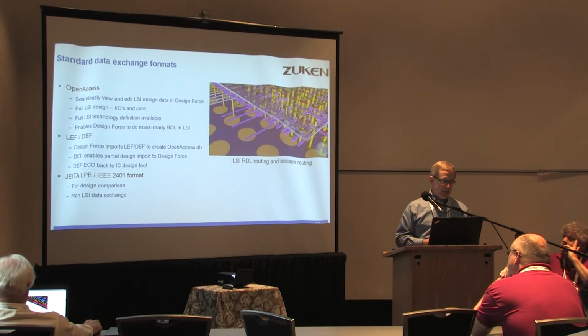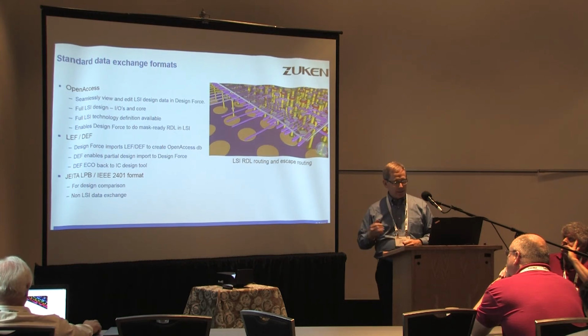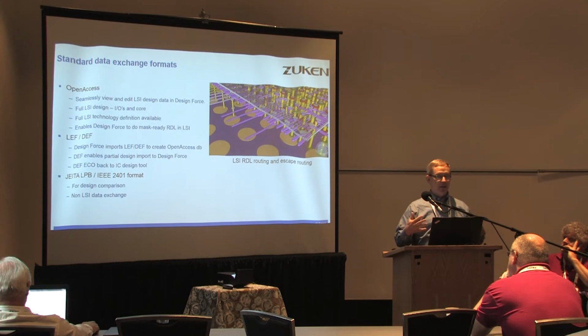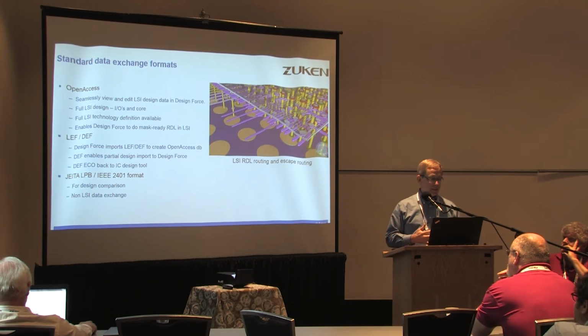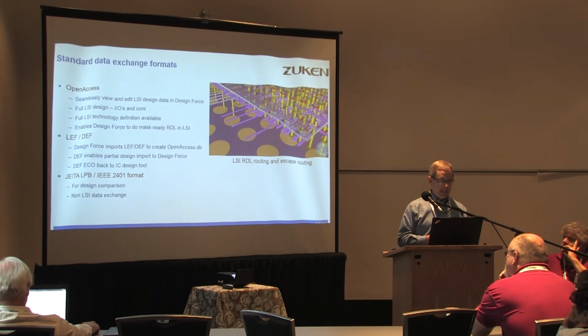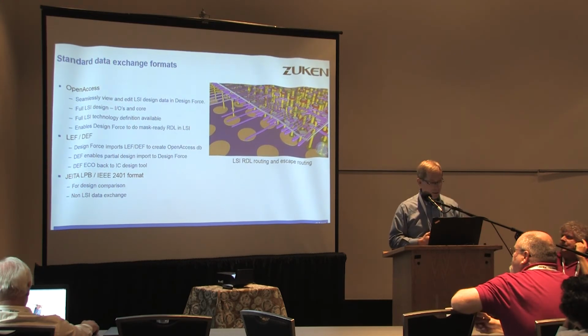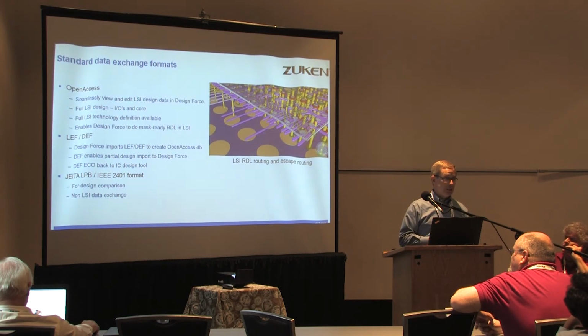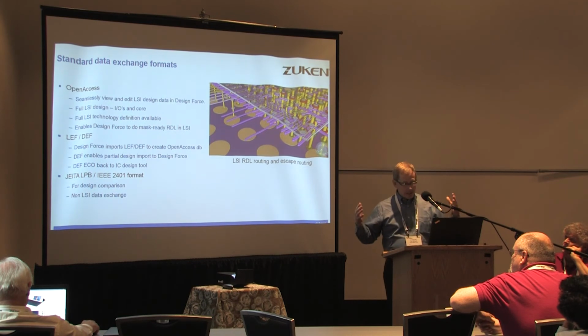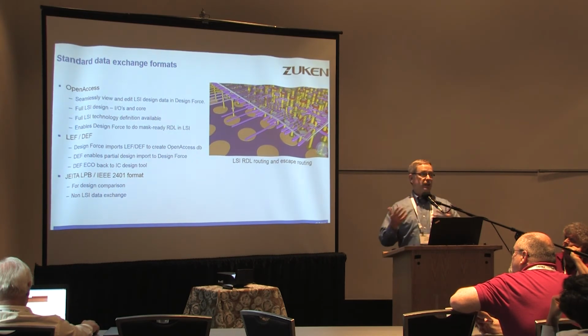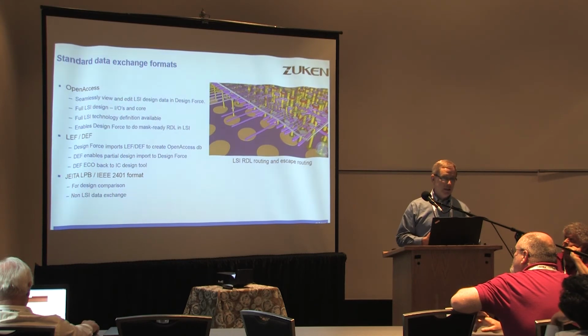So we talked about standard data exchange formats. In Design Force, we use OpenAccess. It doesn't give us everything that we need, but it does give us a seamless view into, and edit capabilities of, the IC from within this traditional PCB design tool. We do use LEF/DEF. There are cases where we've got customers with really huge ICs, and we want to bring in just the I/O pad ring, the bumps, and RDL.